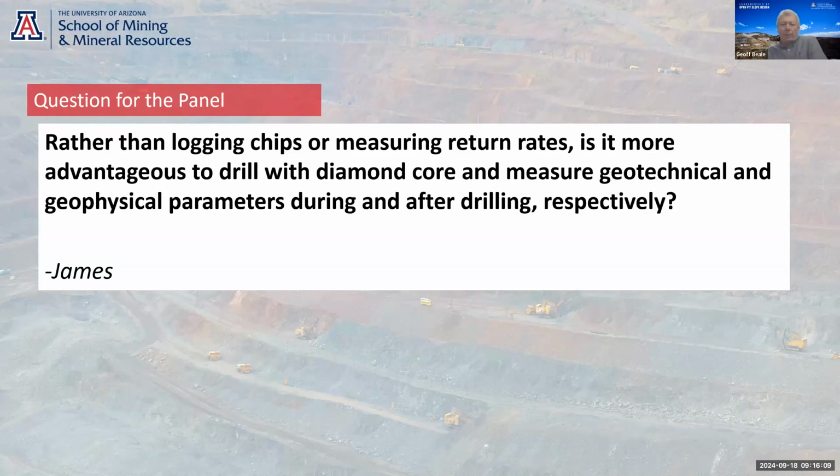Yeah, I think the main thing with diamond core is there's no airlift data, and so you can't actually hydraulically test the fractures, and you can't see what the sustained yield is at the fractures because there's no airlift test. But one thing you can do, and one thing we're starting to push a little more, is injection tests. You can always inject the core holes.